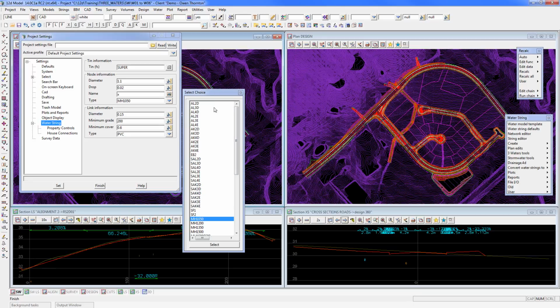In this case though, I've got a series of different pits, and to people who aren't familiar with them, it probably does look rather baffling, but just to break it down in a nutshell, all the pits that begin with type letter A there are the standard type A gully. It's a rectangular pit inlet that's 900 and something by 800 and something millimeters in dimensions, and they're all the on-grade inlets. Skipping over this strange one, EB2, I'll move over to all the pits that begin with S, and they're all the sag configurations, and the ones that are SA are sags of the type A gully, and that's type A gully using the Brisbane City Council terminology.